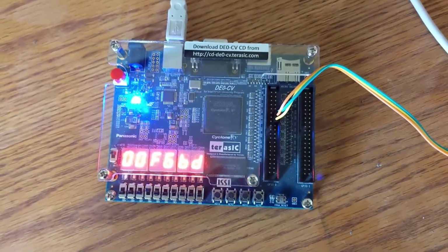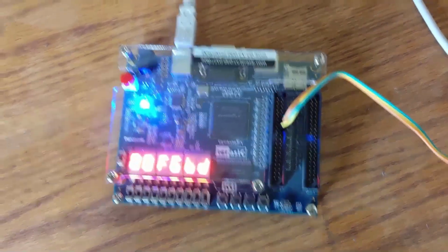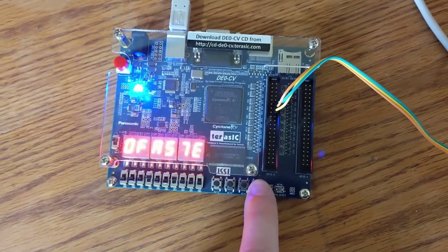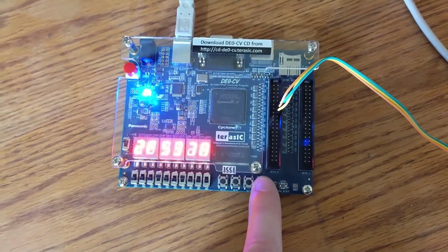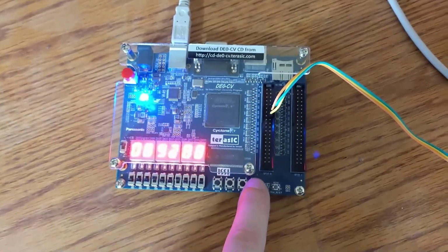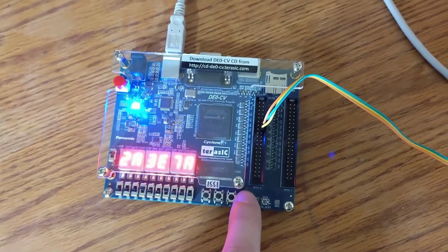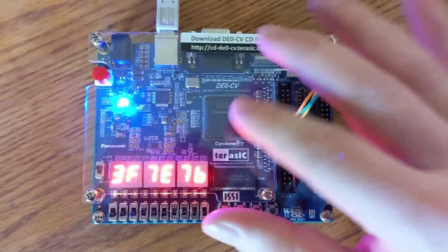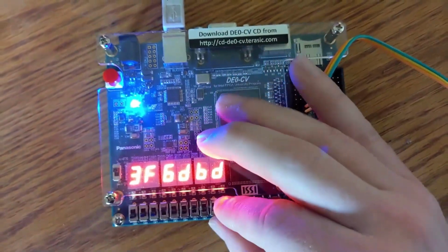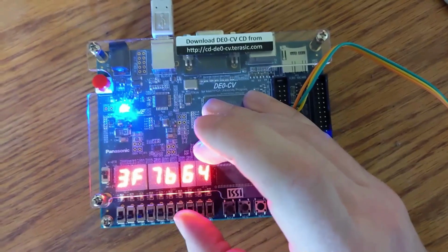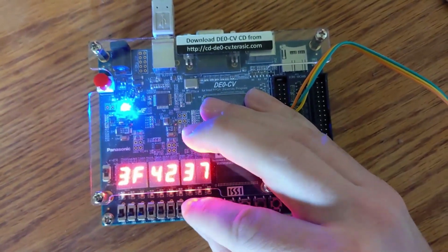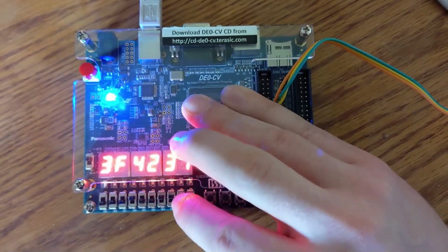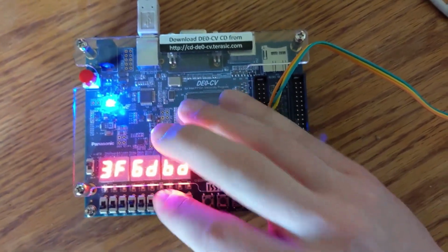It's a double SHA-256 hasher. We have it running on our FPGA board right here. I will speed up and run through the cycles here. Two sets of 64 cycles, but at the end, we end up with our desired output that matches our calculations. Once complete, I can use the switches to select which portion of the output is viewable and match that against our pre-calculated values. This is an important milestone in our project. We now have an unoptimized version that we can start implementing optimizations on top of.